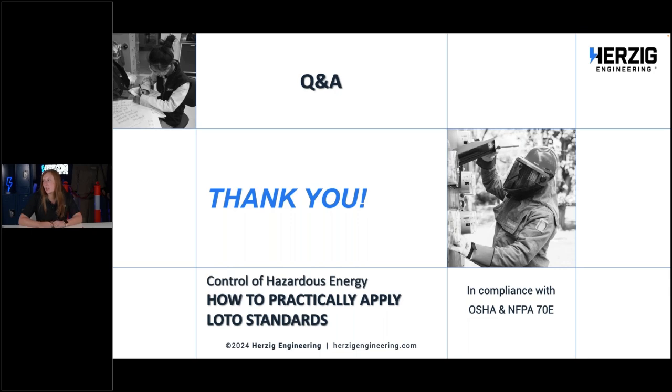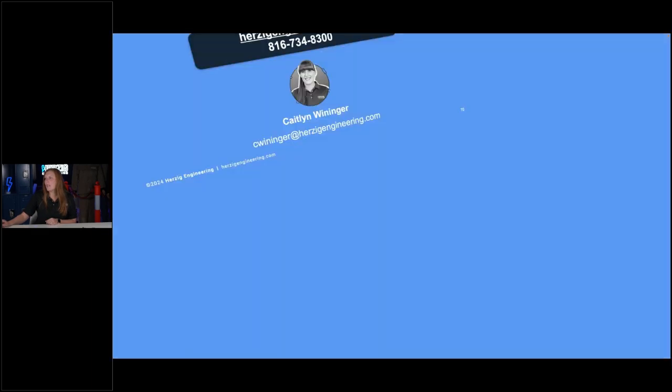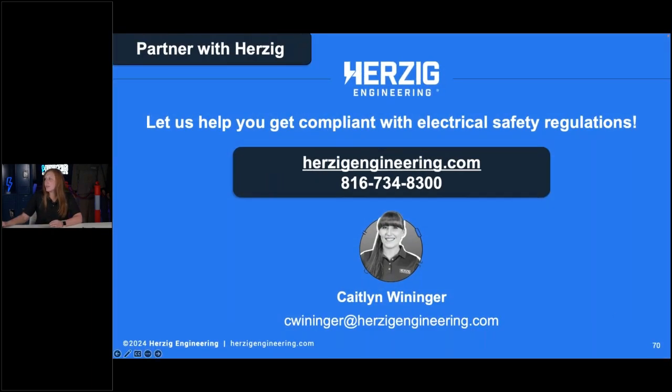Because there's always a chance for an arc flash in those environments. Single phase still can have an arc flash, and some unique systems can. So I would recommend just having a conversation if you're not sure about that. Standard, typically not, but anything 208 and above for sure.